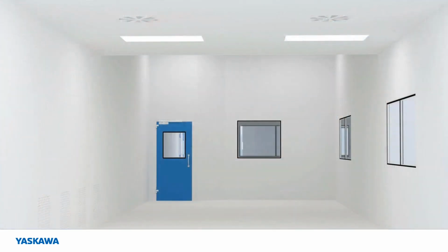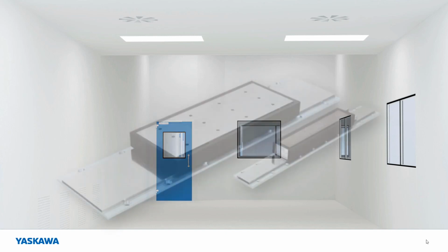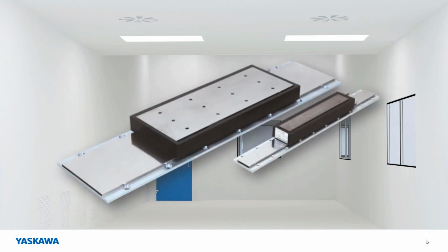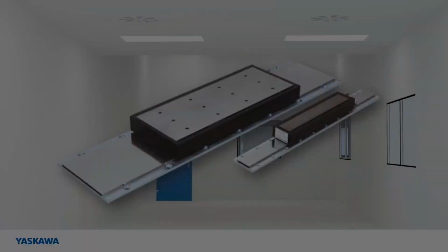Clean rooms are on the other side of the spectrum, where it is critical to reduce the number of microscopic particles emitted by the actuator. Linear motors can be easier to make clean room compatible. The many wear points of ball screws, belts, rack and pinion, or other mechanisms with mechanical power transmission are generally less desirable for cleanroom operation due to the number of particles ejected during operation.